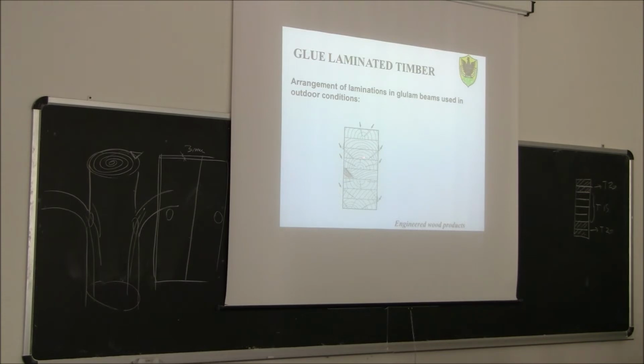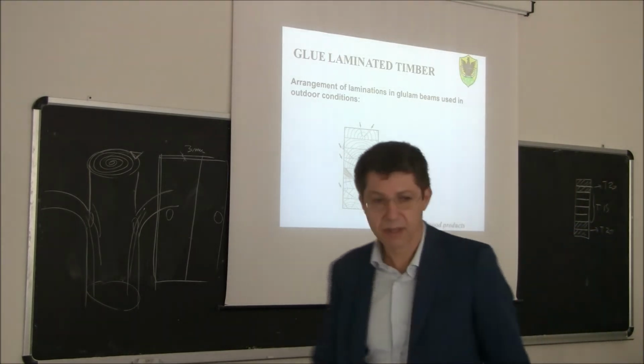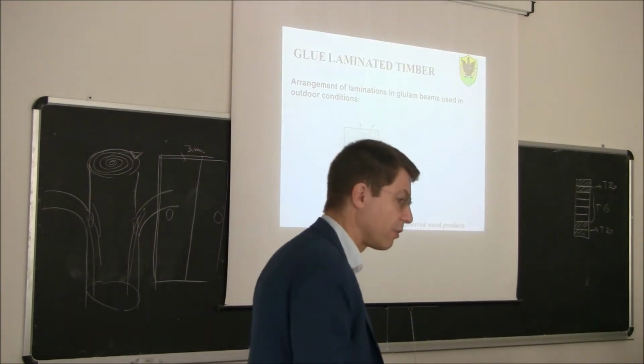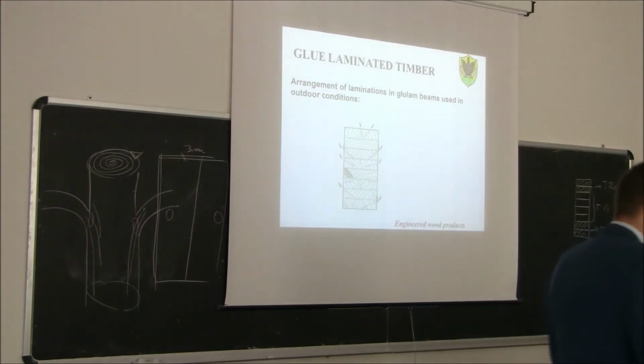If you see cracks like this, and you expose this cross section in outdoor conditions, it's clear that during a rainy day the rain water will just penetrate inside. Once the water penetrates inside, it's very hard for it to get out, and it may lead to durability problems. You will have a specific lecture on durability with my colleague, Dr. Ciometta, so we will discuss this later.